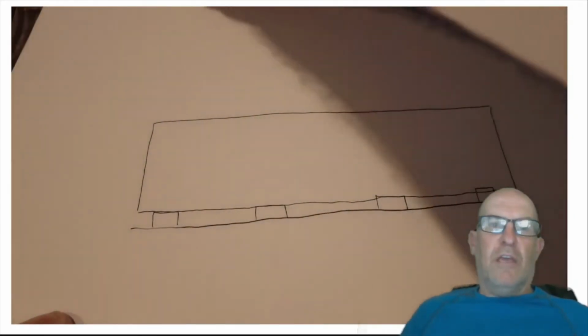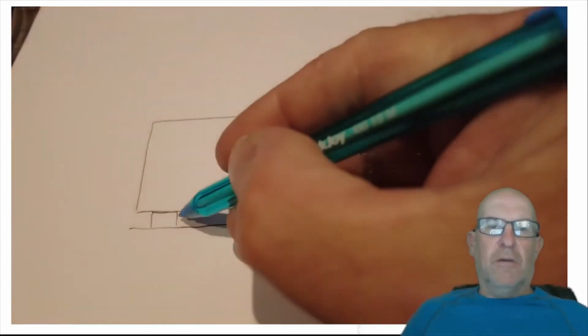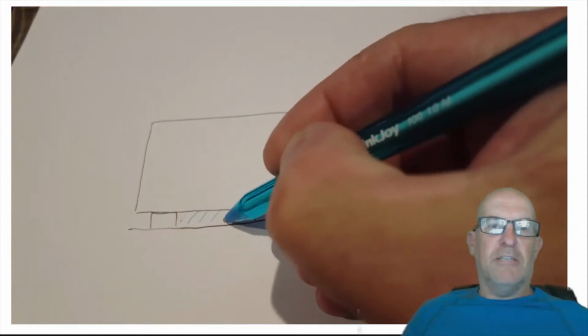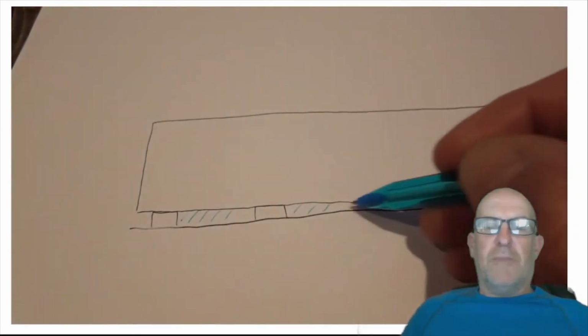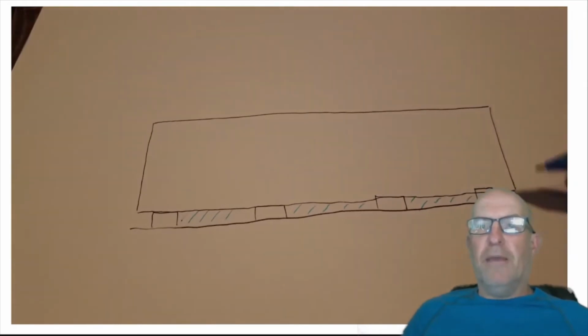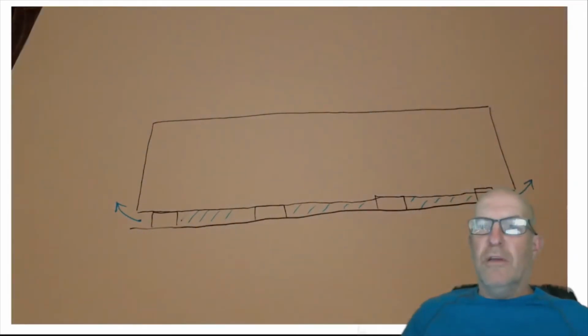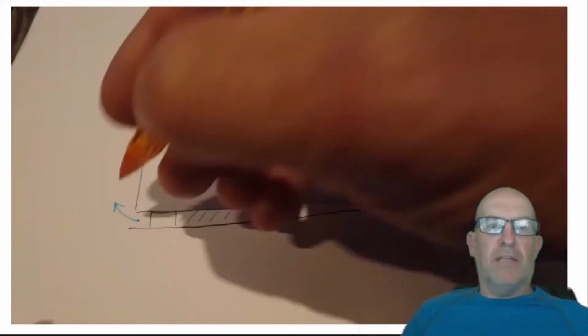And as we can see here, we've got that nice void sitting underneath, so I'm just going to highlight where the clean air space is in blue. So you would expect there'd be some through flow of air. But again, if that footprint gets too big, consideration has to be made for possible stall points or lack of movement in the air. But we've also seen points where people have introduced membranes to the slab.